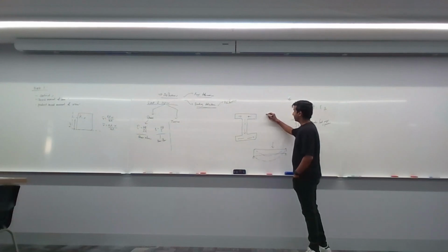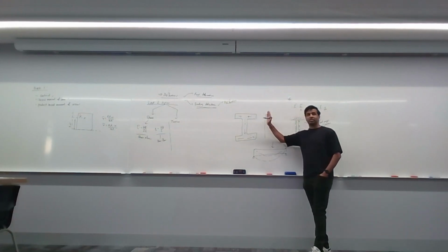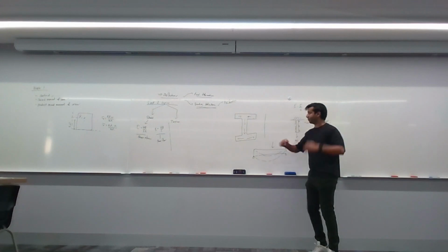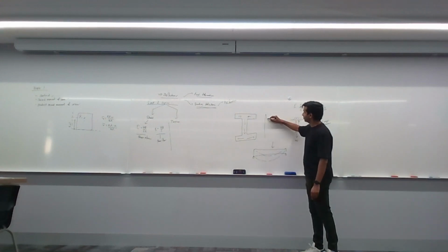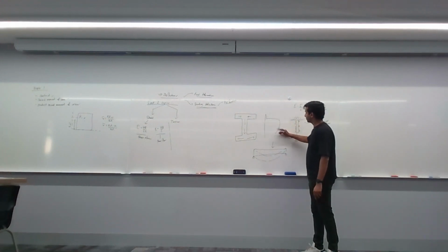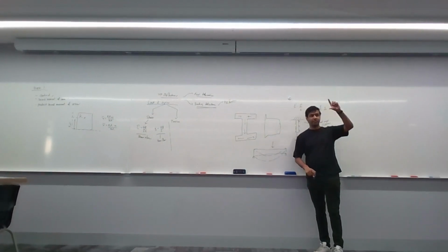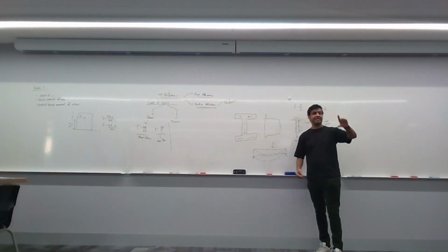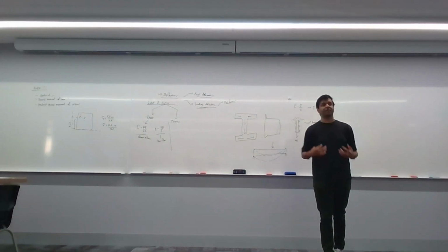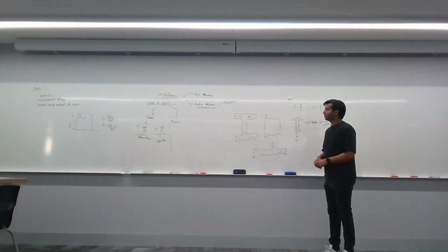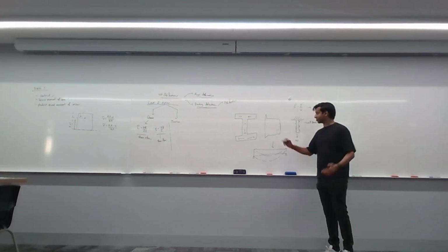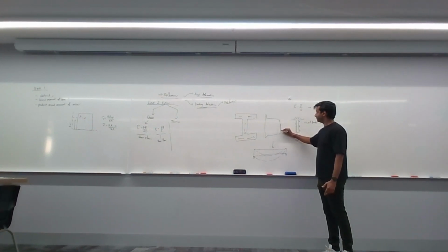Because remember, if I were to graph out how the shear stresses change from the top all the way to the bottom of the shape, it looks like this. The web, the middle part of the cross section, experiences the most shear, right? So how do you calculate the shear stress on any point of this curve?